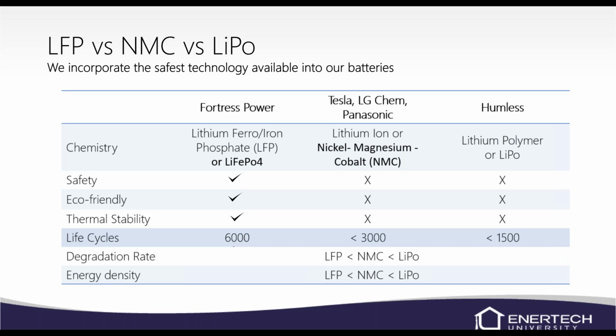And so they've chosen the cobalt style, because it's lighter, and to be hung on the wall, but with cobalt, it's actually flammable. So if anything were to penetrate that battery in a garage, a car, or whatever it may be, then the battery will be flammable. Whereas the iron phosphate will not be flammable.